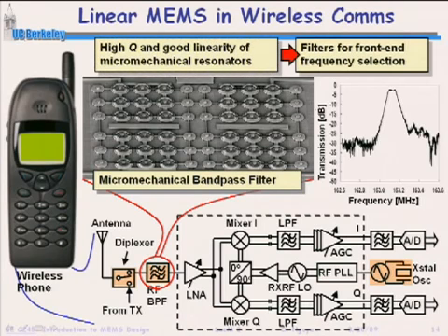Your GSM cell phones use what's called surface acoustic wave resonators, which just by the word acoustic you could tell is pretty much a MEMS technology too. Right? And the inventor of the SAW is in this department. This is Professor Dick White, who's retired emeritus, but he invented the SAW resonator that's basically being used in every GSM phone that's out there. So if your phone does GSM, if you're on AT&T's network, you are using one of his SAW resonators. If you're on Verizon, which is CDMA, you're using the F-bar type stuff.